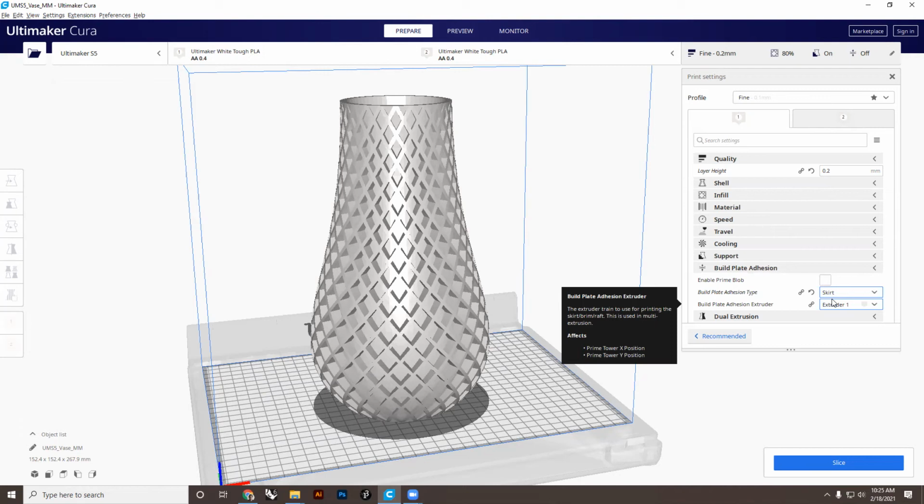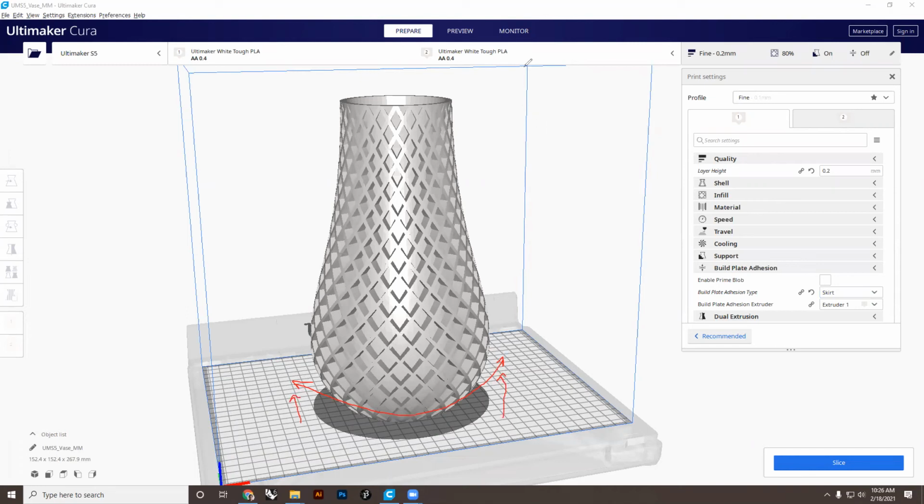This will help act as something that gives it more support, holds that bottom layer down. In PLA printing, you often get a kind of warping that happens on the bottom where your surface will start to peel up as you have your print finish. So you might start to get a little bit of warpage, whereas the material started to cool off, it's actually pulling up and pulling off the build plate. If you leave one of these skirts on, it will essentially give you more print that's offset from here and help make sure that this is holding your print down and giving you better adhesion to the build plate.